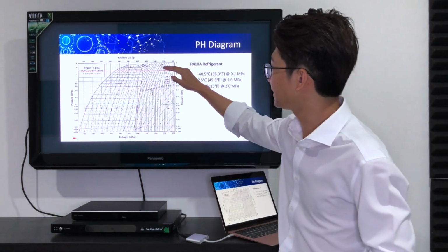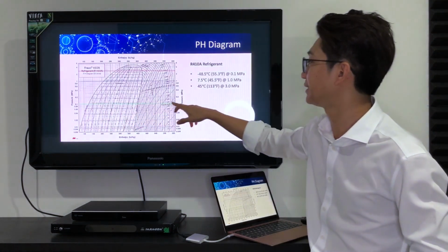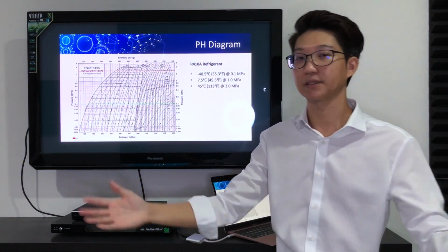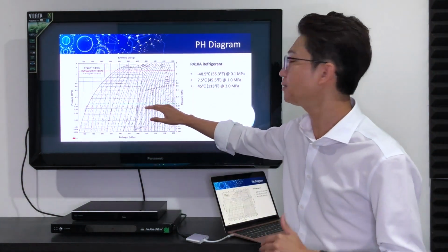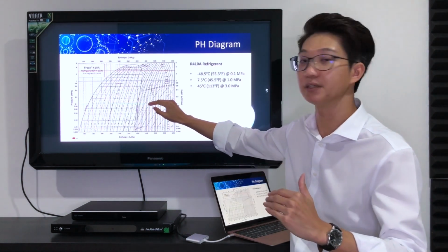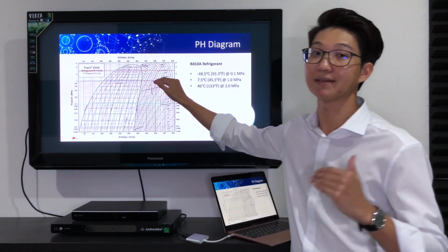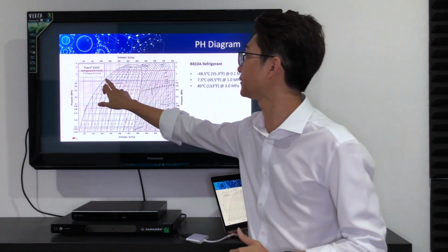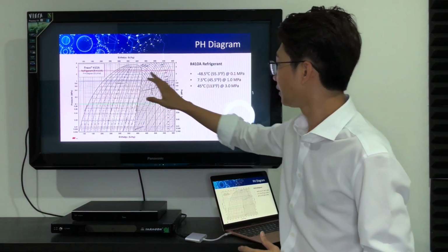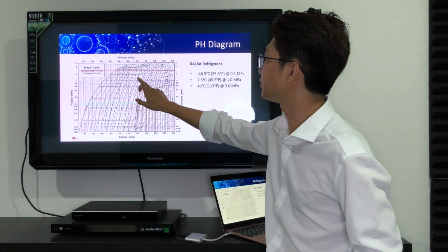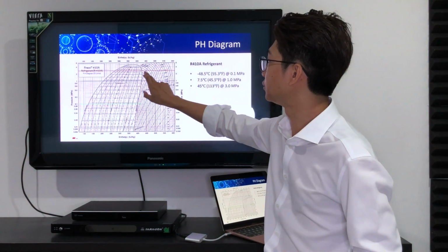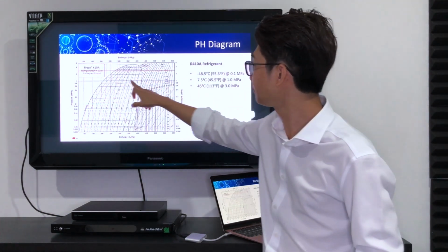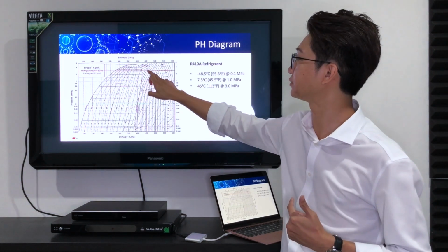So we have three colors here, right? This green line is at atmospheric pressure. Just now we said atmospheric pressure is not useful, not practical, so we are not going to use this line. So now we push the refrigerant up to 1 megapascal, which is 10 times atmospheric pressure. Now temperature here, just now we said 7.5, right? Now how are we going to move from this blue line to this red line, after we absorb everything, right?